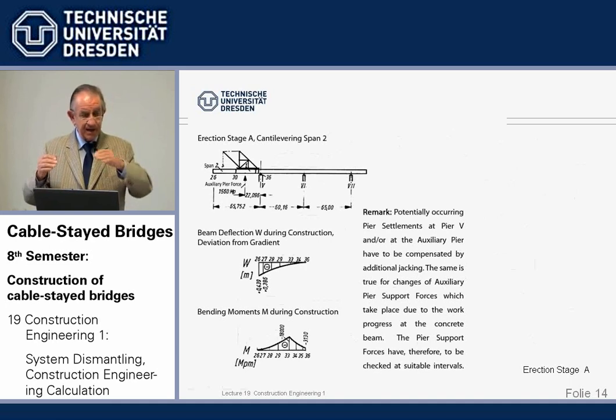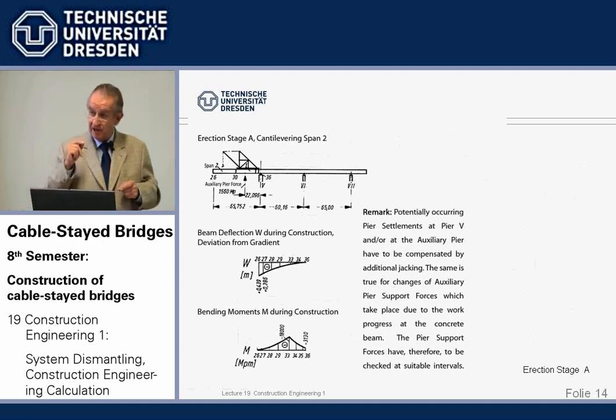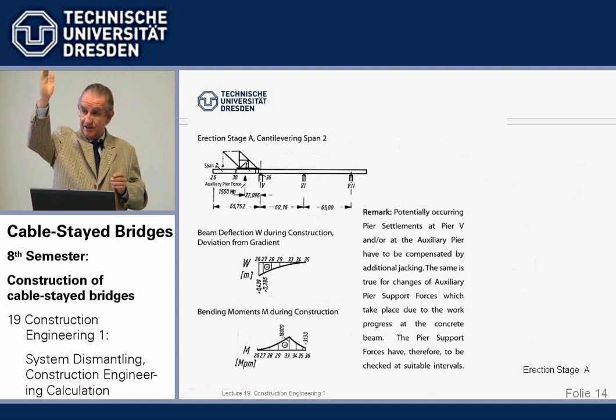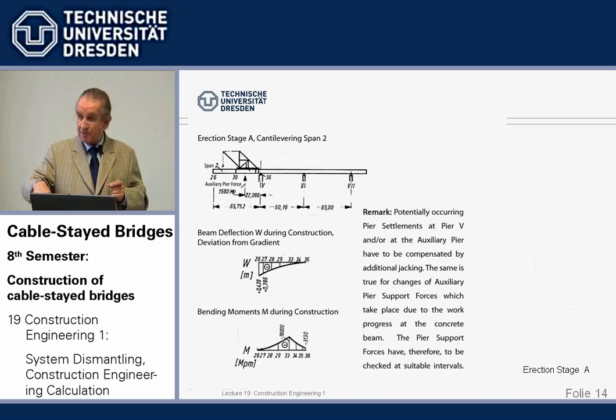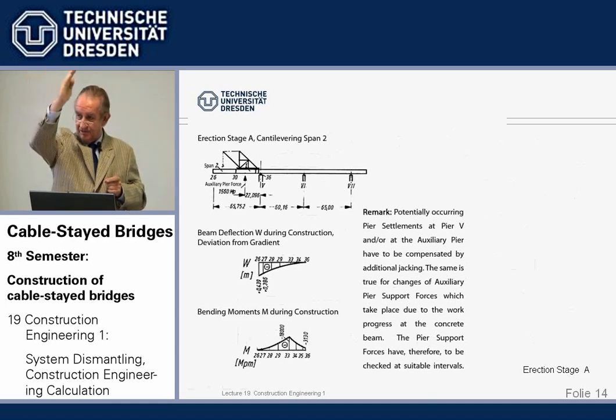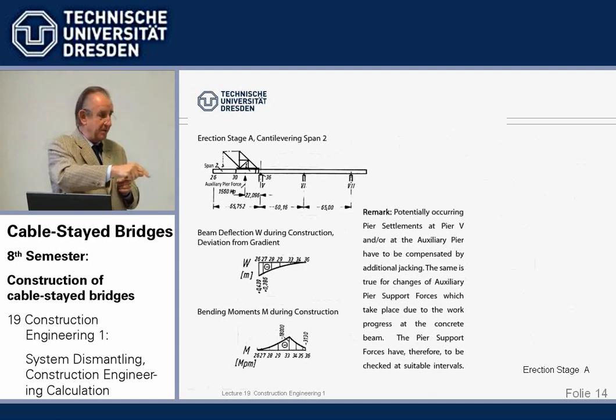And we can check the deformation by a theodolite, just by surveying. We can check the tip movement, and what is very helpful, by the way, we can check the tower head movement by putting on a plumb bob, ein Lot. Now we do it with a laser, but you know what I mean. Down, and you can measure the deviation of the tower head, and that's like a very, very long indicator. That's very helpful. Checking the tower head deformation, checking the beam deformation, and checking cable forces.